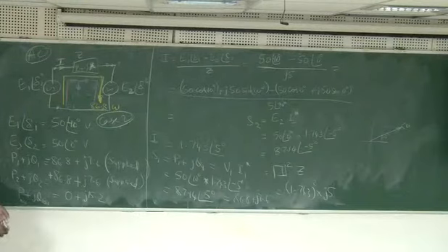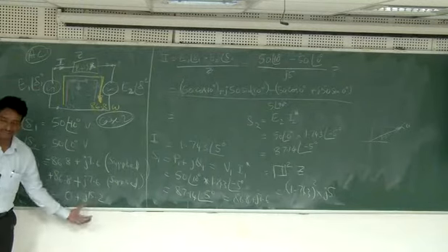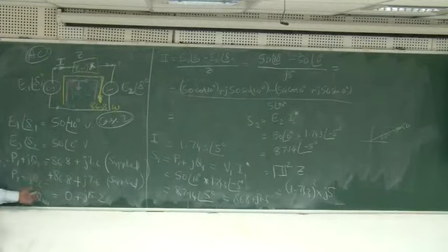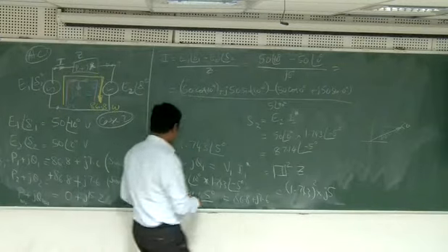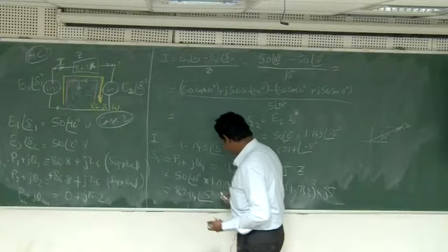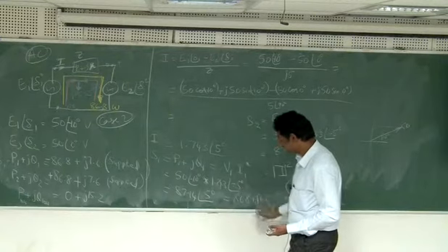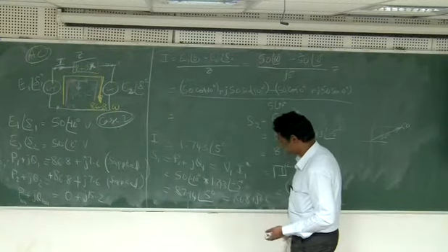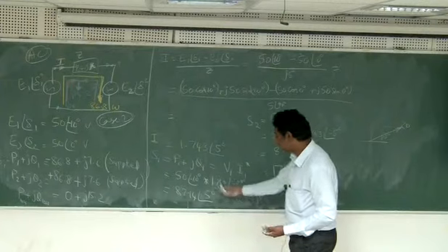So just by reversing the sign of delta, the reactive power flows remain exactly same, just the active power flow direction is changing. So this P1 will be like this, P2 will be like this. So here this is minus 10 and here the current, I don't know what will be the current. Current magnitude will be same.